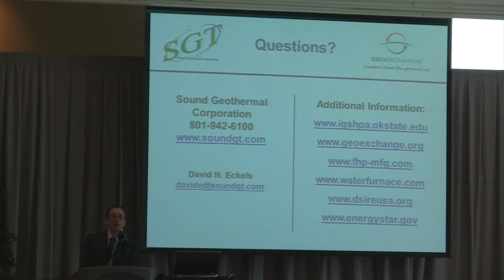The thought process there is that most conventional heating and cooling systems are vastly oversized, and so there's not a huge penalty. The furnace I took out of my house was 70,000 something BTUs per hour, and I put in a 3-ton or 36,000 BTU an hour heat pump, and I did the load calculation myself, and it works beautifully.